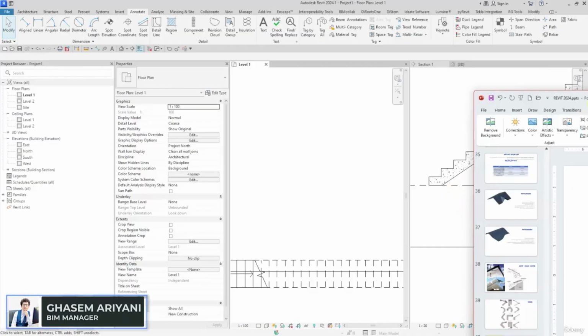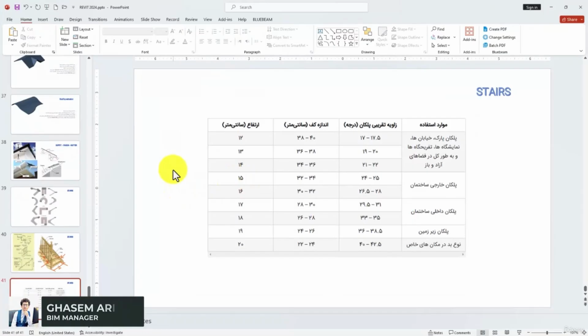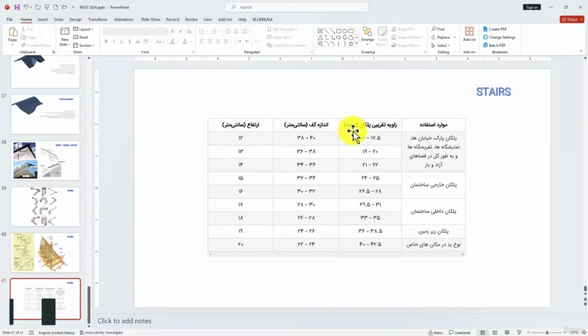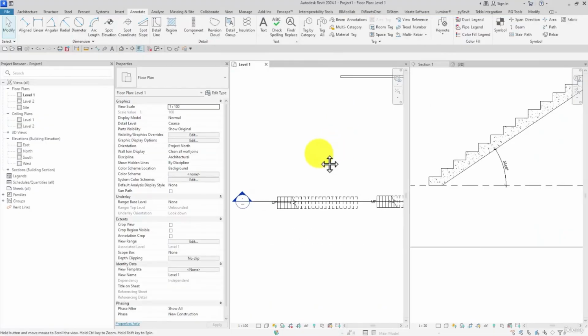According to the explained items, here we can use these values for the number of the steps, riser depth or width, and also the tread in the basement, in parks, streets, exhibitions, the stairs inside the buildings or outside the buildings. For instance, outside, the angle should be 24-25 degrees, and then the tread depth is 32 to 34, and the height of the steps or riser is 15.